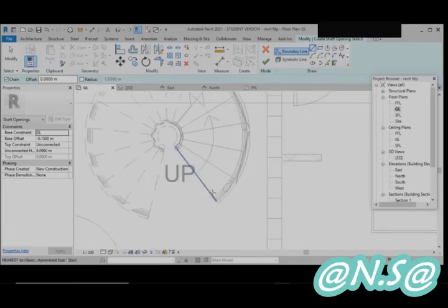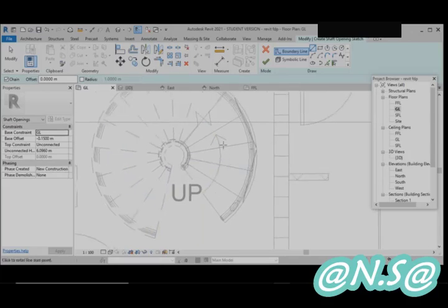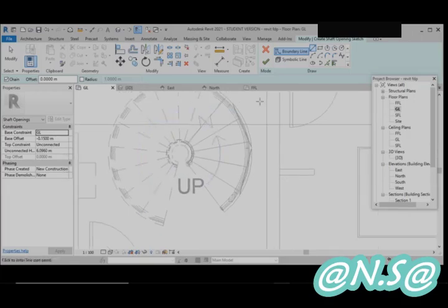So this is our downwards. Here we have no need of an opening, but near this upwards region, as a person goes up, the roof will obstruct him. So we need the opening in this portion, right? So let us create the opening. I'm just choosing this pickaxe tool, and from this part I need the opening. I'm starting the opening, and I'll just draw the opening